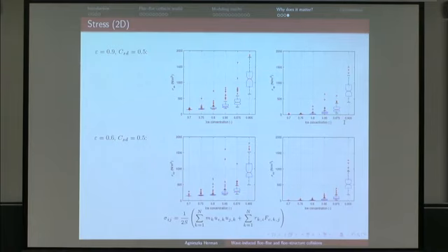And in the perpendicular direction, first the stress is usually zero. We almost have no collisions in the direction perpendicular to the wave propagation direction, and then the values get larger. And in most cases that I analyzed, at large ice concentration, this stress component is between 60 and 80% of this one.